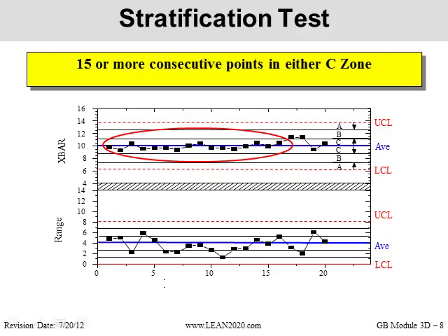Another condition that you would be looking for is maybe something changed in your process that made your process better than it should be. My process should not be operating as tightly as this, and I want to find out what caused that. This is a condition that's actually preferred, right? We don't want to have a lot of variation.